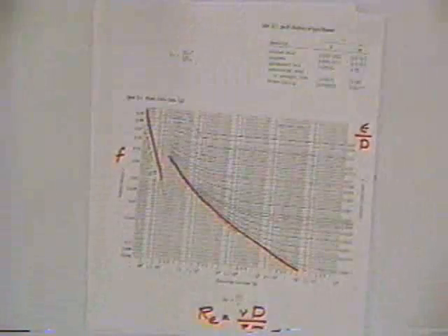And so, by definition, a smooth pipe is a pipe where the roughness, this epsilon, the little height of the roughnesses inside the pipe, is small enough so that the laminar boundary layer, even if you have turbulent flow in the pressure conduit, at the contact between the liquid and the boundary, there will be a laminar boundary layer. Now that laminar boundary layer completely covers up the roughnesses. Then the flow turbulence never sees those roughnesses. And we call that smooth pipe.